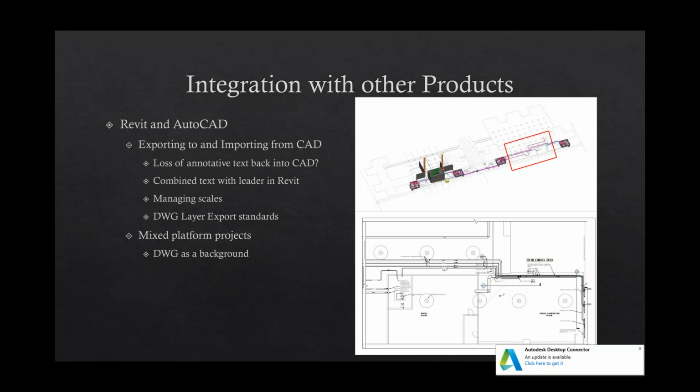The only time I've ever seen an exception to this is this project where we said, you know what, this needs to show in every view, because it's effectively simulating the architectural model. That was the one time I loaded it to the 3D space itself onto a proper workset and with due caution. But otherwise, always load your CADs to view only, lest they show up everywhere or unexpectedly. And linking is way better. And with that,